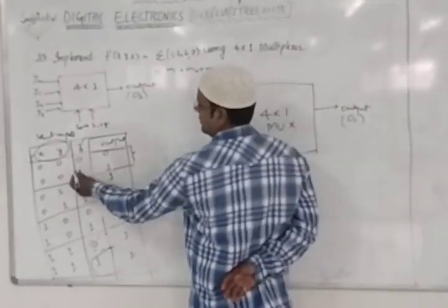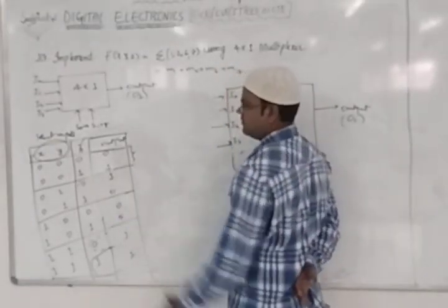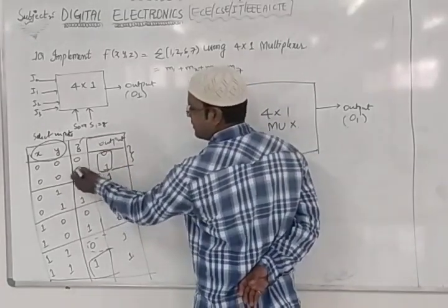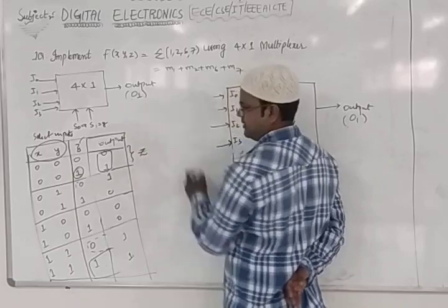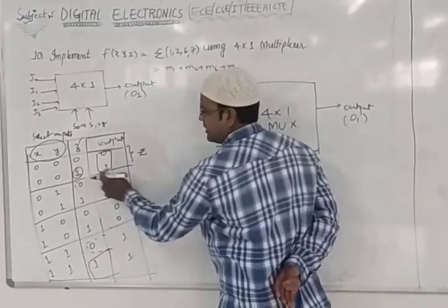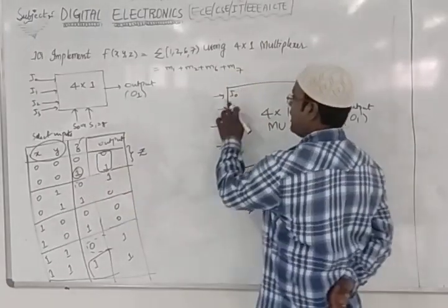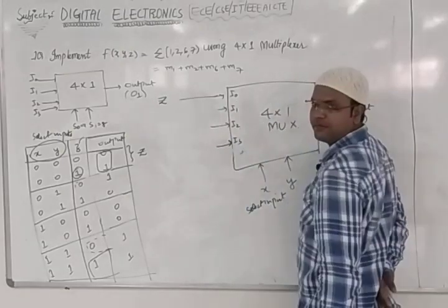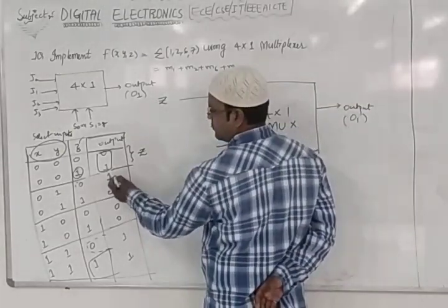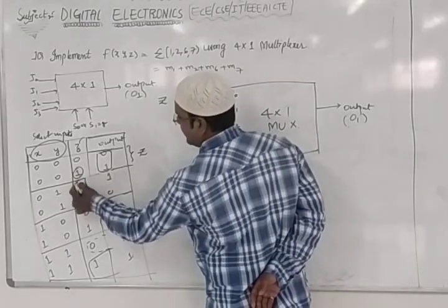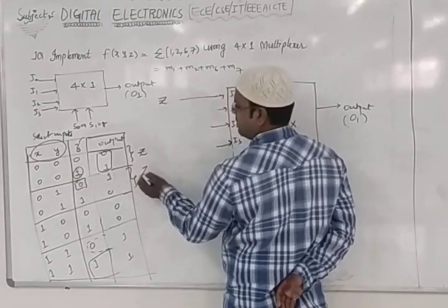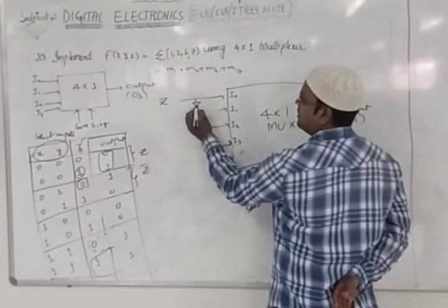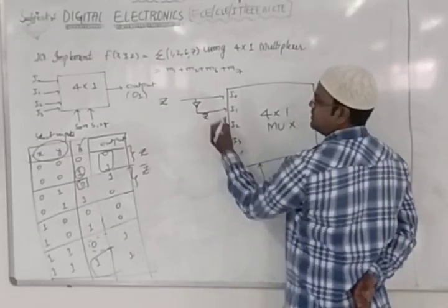So tell me, this is varying, right? So 0 and 1. One time it is 0 and another time it is 1. So I'll see only this one. So I can write this as Z, because when Z is there, it is high. So for I0, what I am writing, I am taking one Z. Directly I am passing. For the next, rest of 2, when it is high, when we had Z bar. For these 2, I'll mention it is Z bar. How do I connect Z bar? I'll connect one NOT gate, I'll pass it, this has become Z bar.